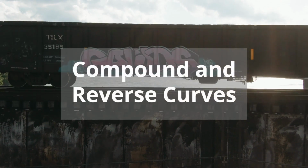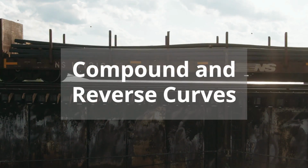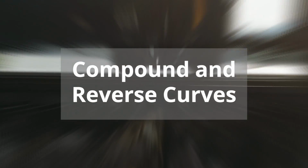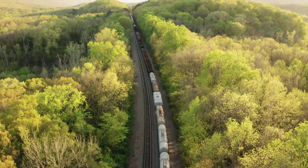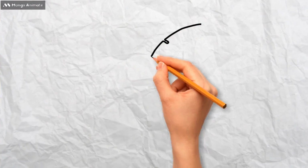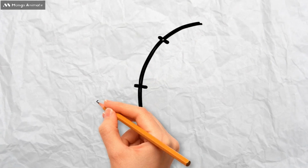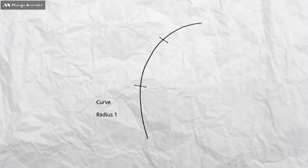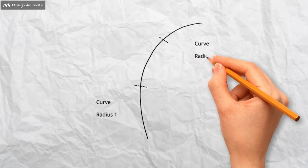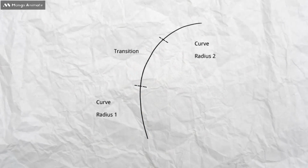In addition to simple, single, curve arrangements, there are also compound and reverse curves. Compound curves are where curves of similar flexure are placed one after the other. This could be because the curve needs to become tighter or looser in radius. In between these two curves, there should be a transition, the same as between a straight and a curve.